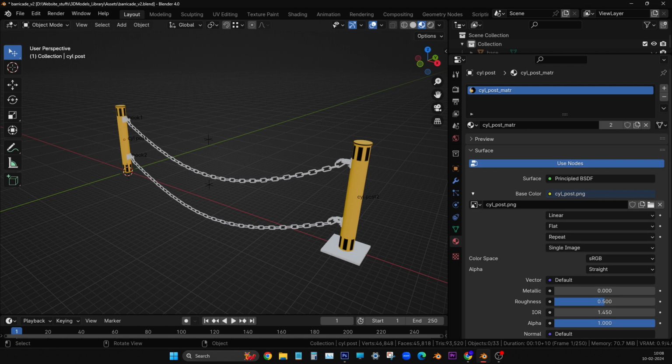So now you can Alt A, go to add again, and come to lights. Light is there, no? In that, you choose spotlight. Yeah. Now I will show you. You can just move it and keep it upwards. Go to the move icon in the toolbox and move it up, so that it will be visible. Whenever we create something, it will come in the world origin, so we have to move it that way.